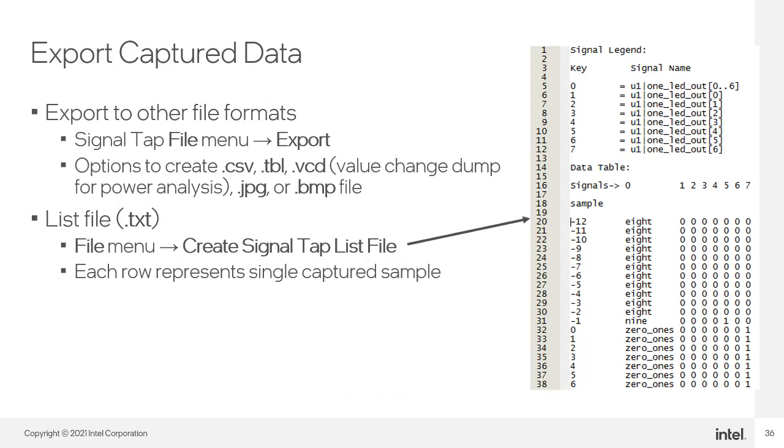The captured data can be exported to the multiple file formats listed here for use in other tools or for documentation purposes. Export the captured data using the Export command in the Signal Tap or Intel Quartus Prime file menu.